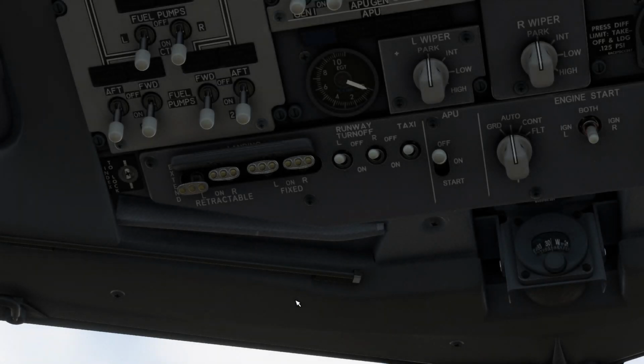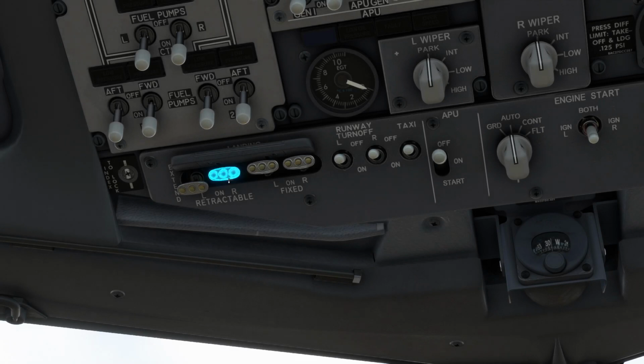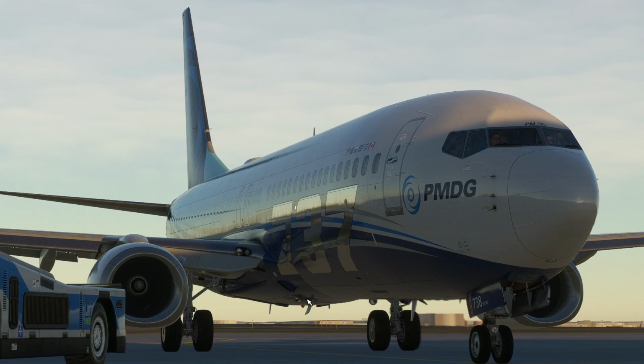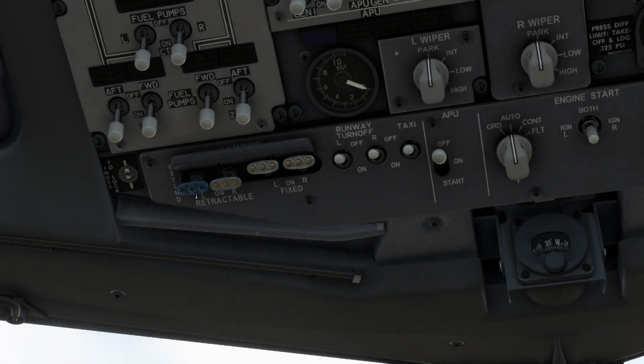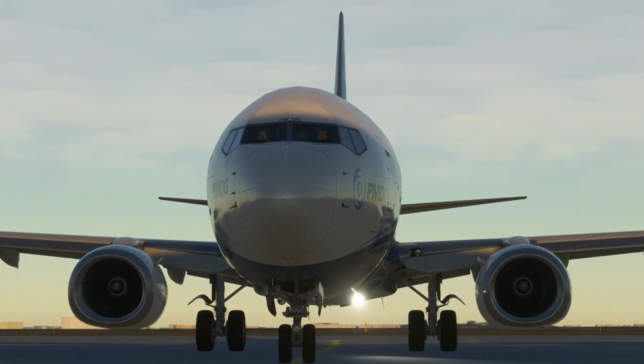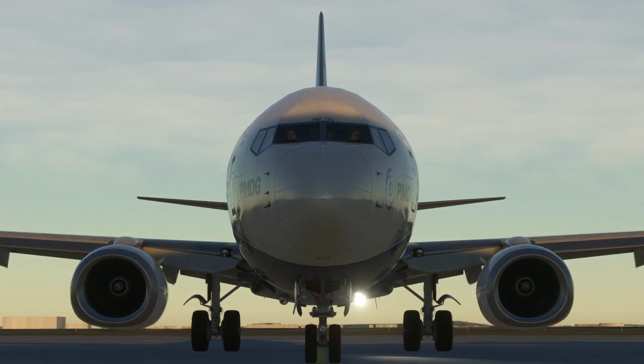So I go quickly inside, and now on the right one I'm going to take it to the mid position of this switch, and you're going to see this light being extended. So it's been extended right here now. The mid position only extends the retractable landing lights, and the down position then turns them on. As you can see now we have the left side on.